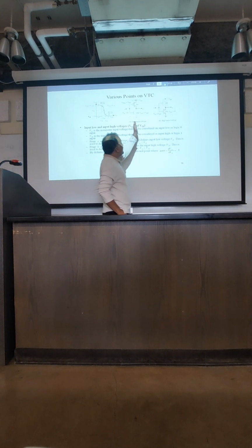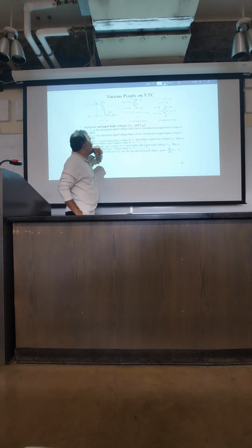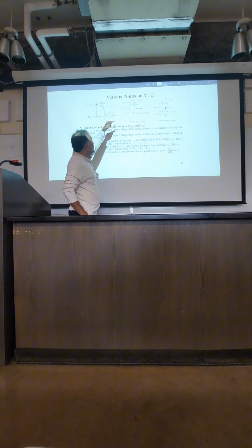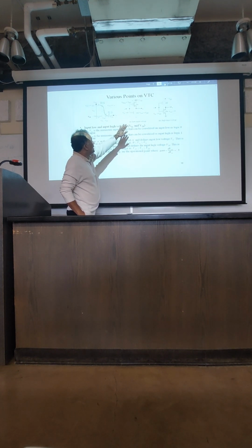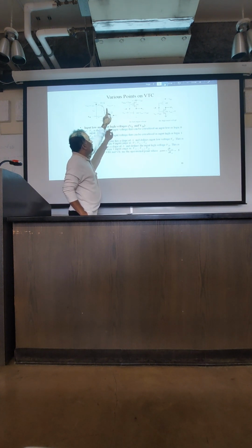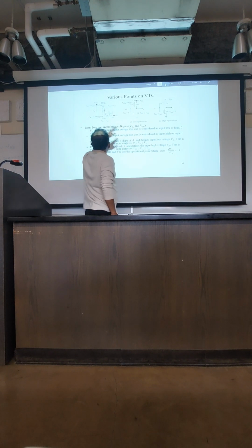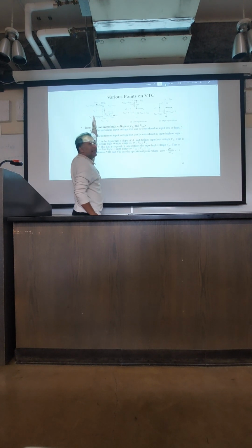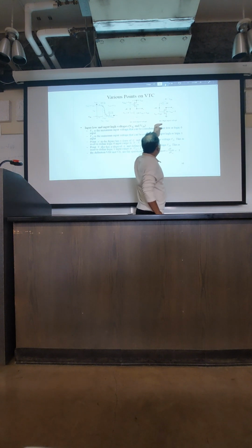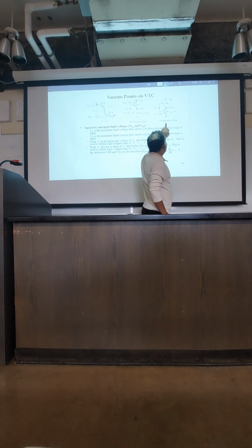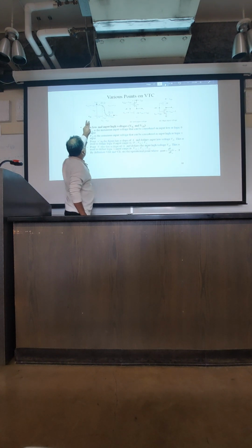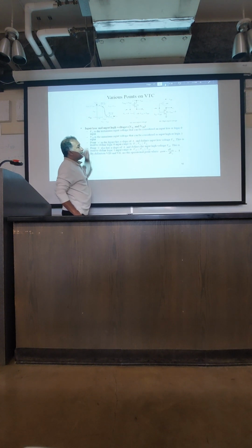So now let us look at the different switching scenarios for the CMOS inverter. If input is 0, we know that NMOS is off, PMOS is on, and PMOS can take the output all the way up to VDD. So VOH will be equal to VDD. If input is high, NMOS is on, PMOS is off, and we know that NMOS is a good pull down, so output will go all the way down to 0. So our VOL will be a perfect 0.